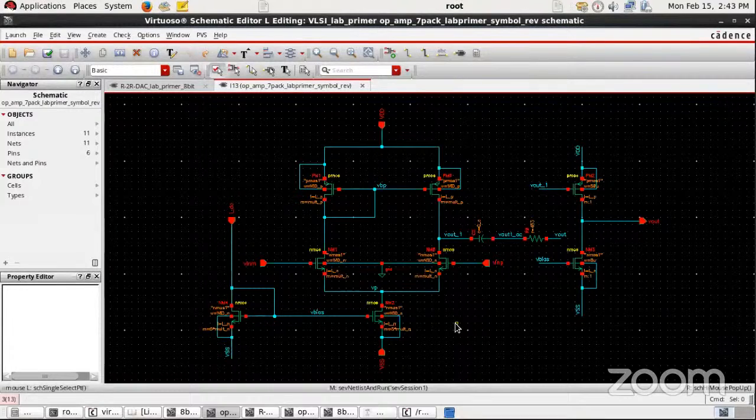And we have the compensation capacitance and compensation resistance included in the circuit, in order to improve the stability of the amplifier. And this ladder network can be compared with the ideal block that is available within Cadence also. So how did we do that?